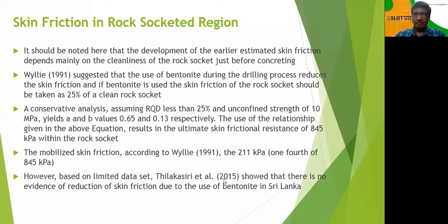But later we found that, when we did the instrumented pile load test, right? Through the instrumented pile load test, we can actually measure the mobilized capacity. If you measure the mobilized capacity, we found that there's no effect of the bentonite slurry. It is evident from the results that there's no effect of the bentonite slurry.